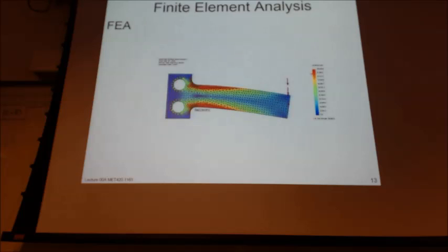We also have to be careful when we're assuming linearity as it relates to geometric concerns. So what do I mean by that? If you have an object that has a large amount of deflection, then it might have to be analyzed in a non-linear way because it's moving too much. Also, materials have geometric stiffening. This is as the tensile stress increases, the physical part will stiffen, and this is not to be confused with strain hardening, which is a change of properties.